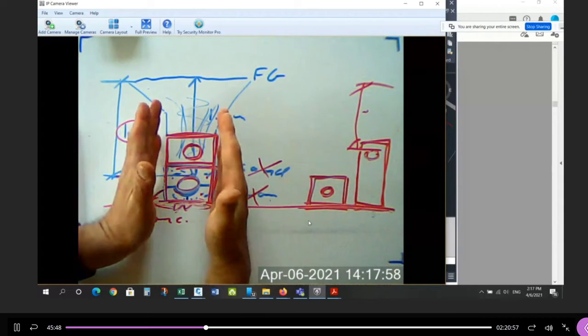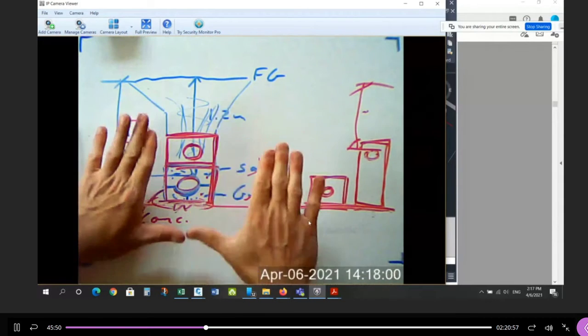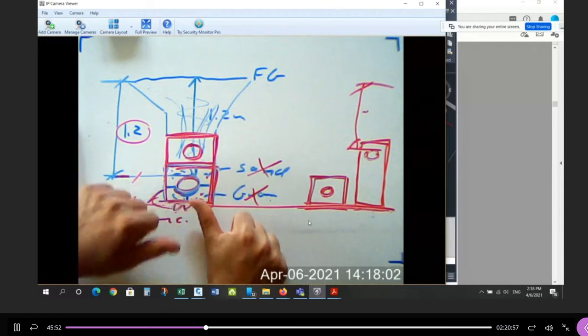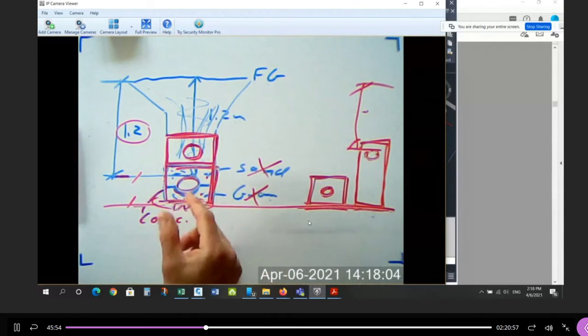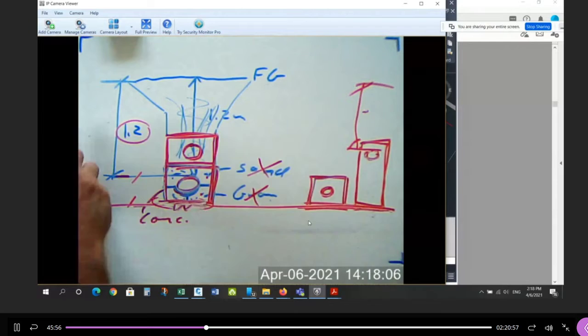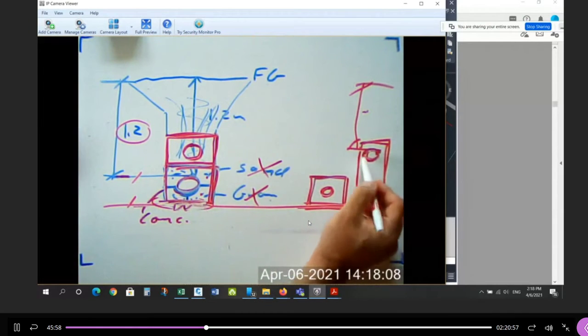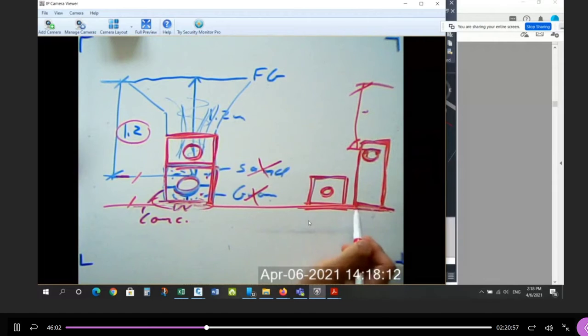So the thing is, if you're going to lift this block of concrete, it's hard to grab it from the sides and push it up. You really need to get underneath it. You have to get underneath it to push it. Well, if you prevent freezing underneath it, then you're frost protected. So even though the pipe is below frost protection, the structure that it's encased in is below the frost level. So this might have freezing in the sides, but never underneath.